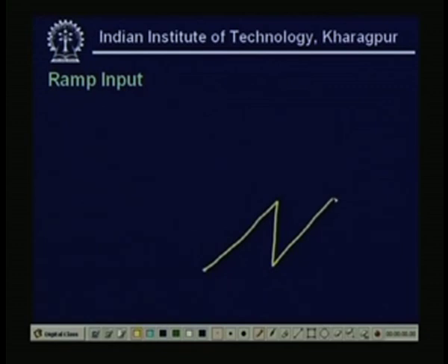In many electrical circuits you give this type of waveform. One common example is the cathode ray oscilloscope, where to measure voltages, the voltage amplitudes are given between the y plates, and the sawtooth waveform is given to the x plates to synchronize or make the wave stationary.